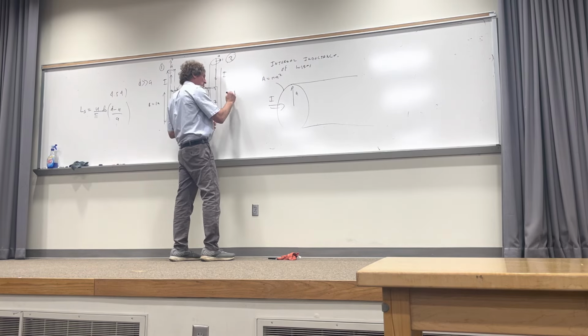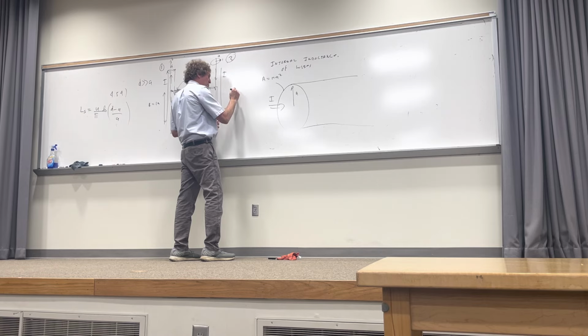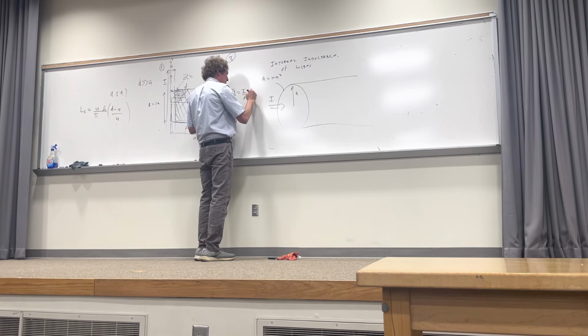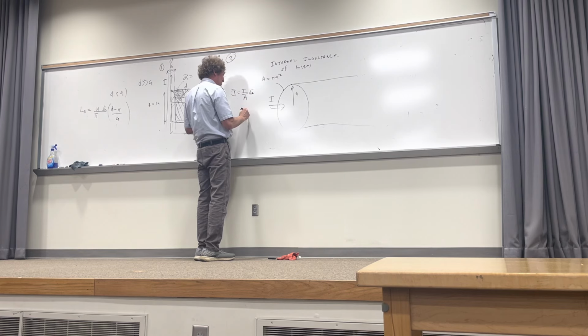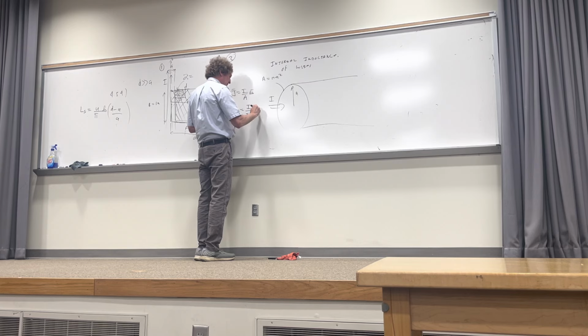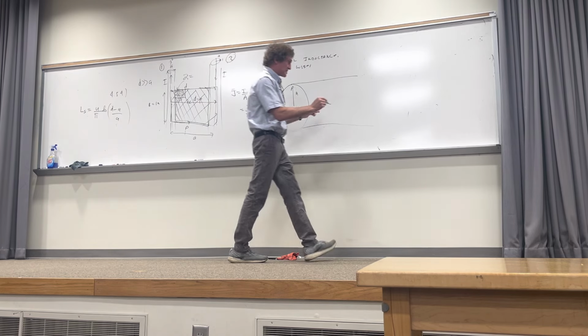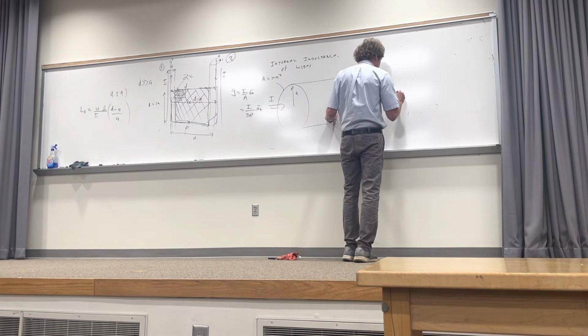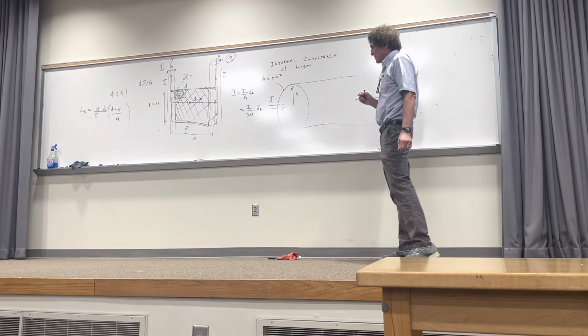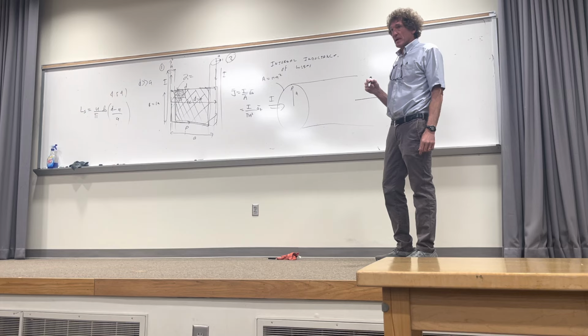And that would give me a current density inside that wire, J, of I over the area, and call it az, which would be I over pi A squared az. I'm gonna call this axis, this the Z axis, to make my life simple. Y'all with me on that? You agree that that would be J?